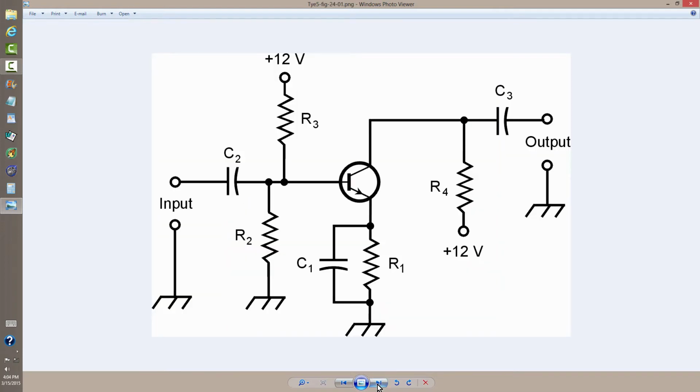But here is the real gist of this video. A basic weak signal amplifier design. It is a Class A amplifier using an NPN bipolar transistor. The signal enters here. Microphone, antenna, anything where the peak-to-peak voltage is very, very low, so it's a weak signal, like you might use in a radio receiver or a microphone amplifier, for that matter, a sensitive sound meter.